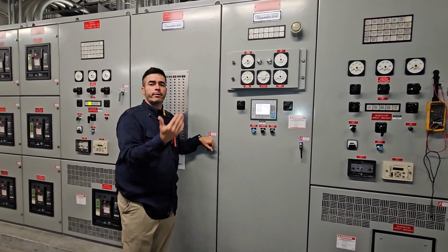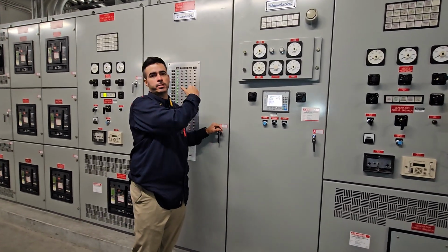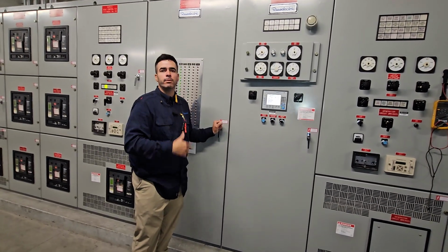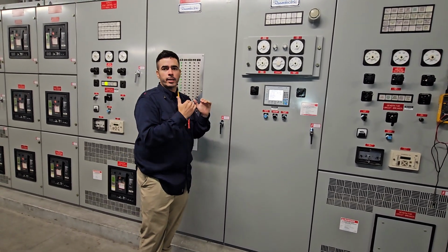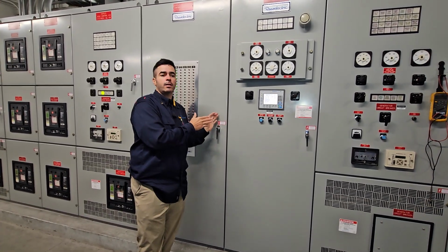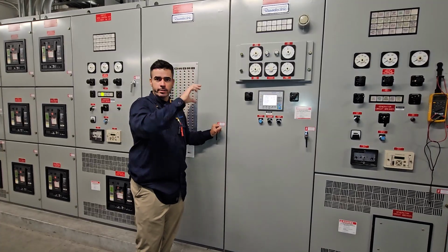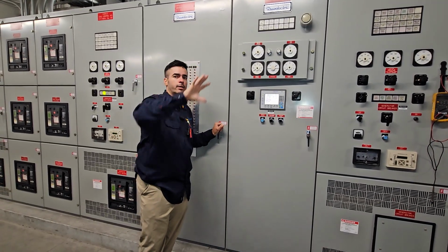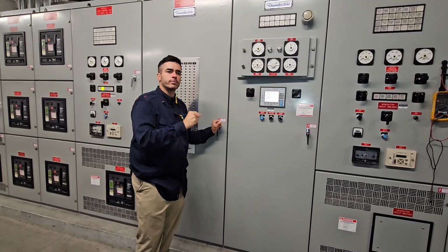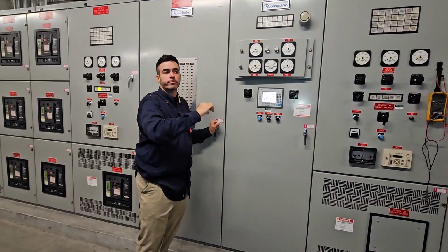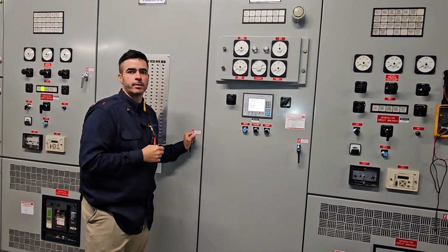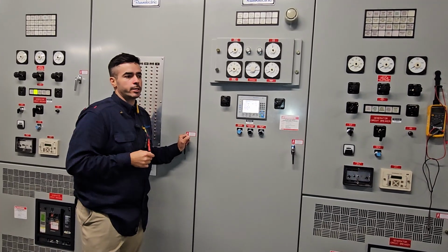Under an outage condition, when you lose the normal source, that one goes right away because there is only one source to go to, okay? But in this case, that's why they take long. And the reason why it might be, and the other ones are not taking that long, is that the controller is not calibrated correctly. All these controllers are already outdated, so they need some calibration. Sometimes they're reading 58 hertz when you actually have 60 hertz, so they will take too long to transfer. But that's something that we can adjust.